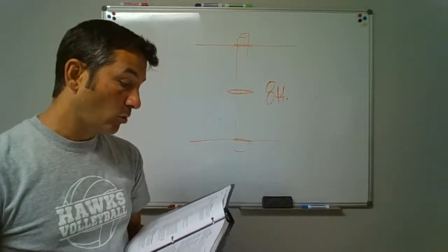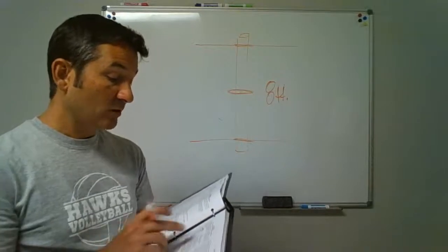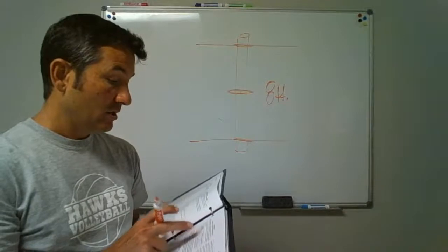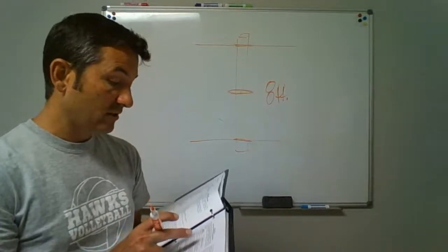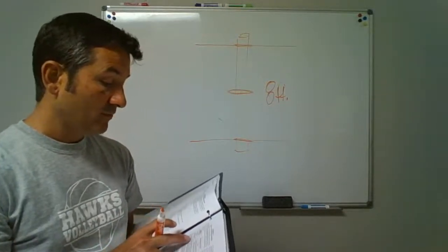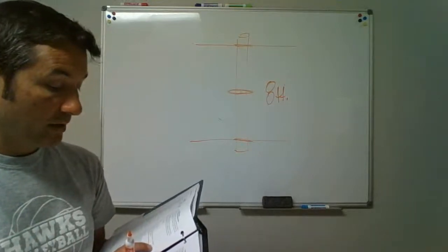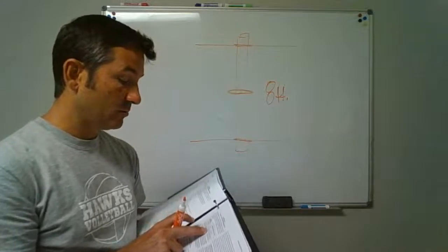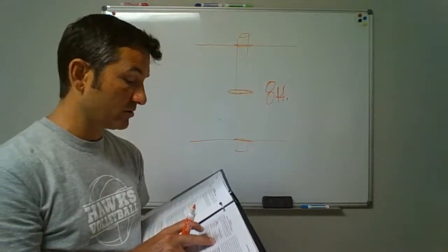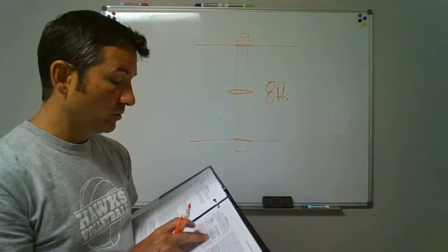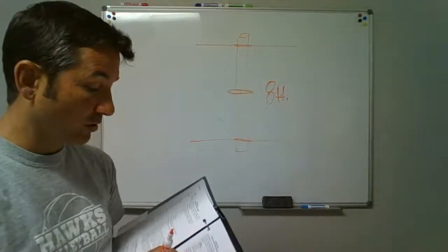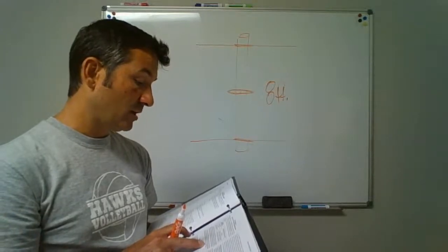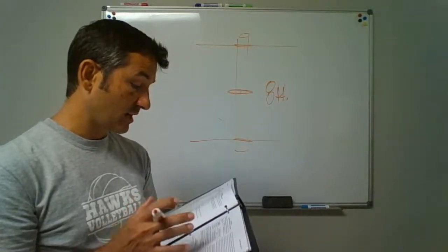toilet facilities for workers. It is required by code that toilet facilities should be provided for construction workers. Construction worker toilet facilities of the non-sewer type shall conform to this: if you've got less than 20 employees, you have to have 1 toilet. 20 to 200, 1 toilet and 1 urinal per 40 workers. More than 200, you got 1 toilet and 1 urinal per 50 workers. Okay. There should be at least 1 facility for every 2 contiguous construction sites.